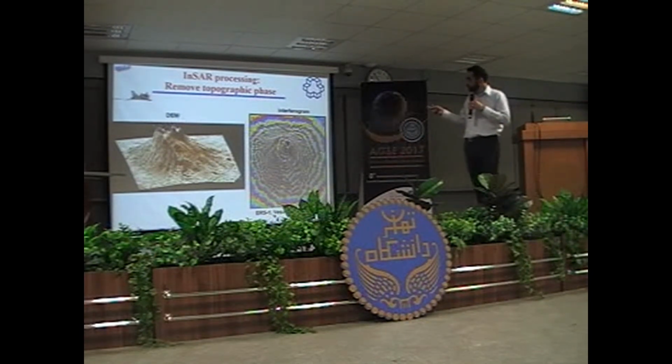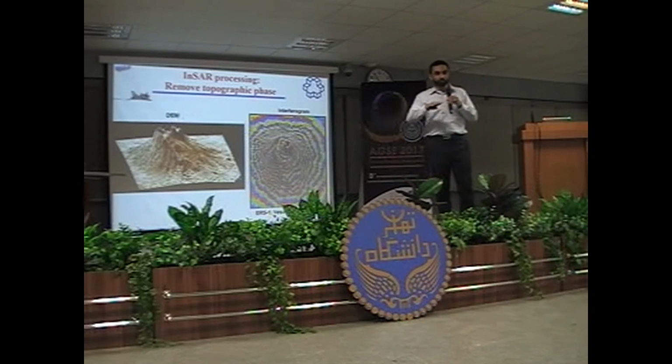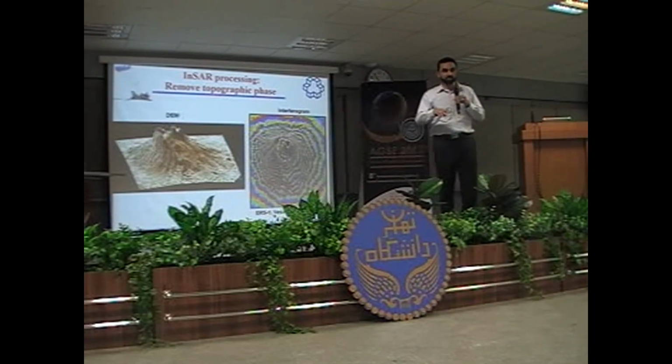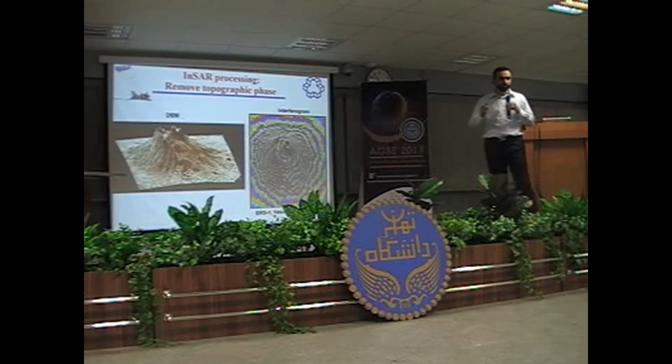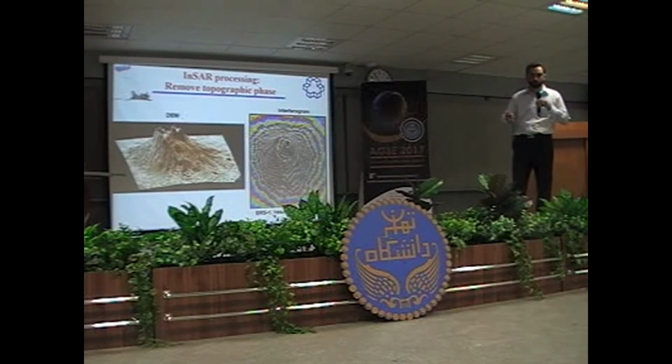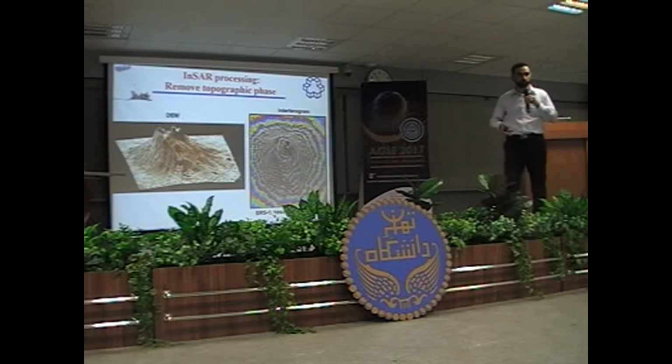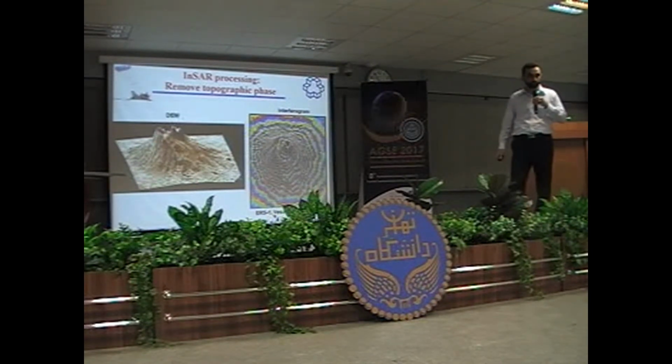But when you are using this technology for subsidence monitoring, the accuracy is in the order of millimeter. That's totally different. For subsidence monitoring, it's very accurate. But for DEM generation, actually, there are some involved parameters like the baseline, what baseline you are using, what wavelengths you are using. But generally, the accuracy of the DEM that is generated here is in the order of 5 to 10 meters.